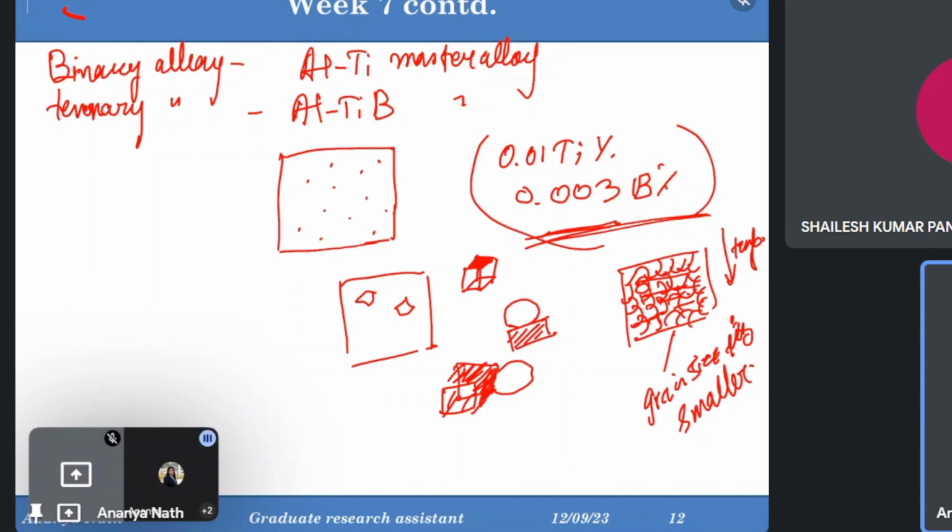So there are two things. One, the number of facets. Another one is the lattice orientation. Low mismatch is needed, because with low mismatch there will be less energy needed to nucleate, so low mismatch is always preferable. So the intermetallic morphology is important in terms of the number of facets and the relationship with the lattice orientation. For example, if we are using the Al3Ti intermetallic for nucleation, the 112 plane will be the preferred site for alpha aluminium to nucleate.